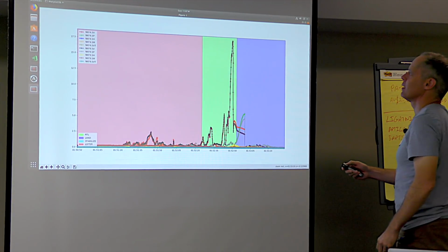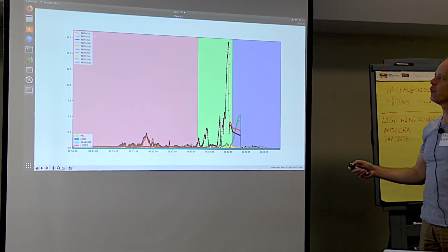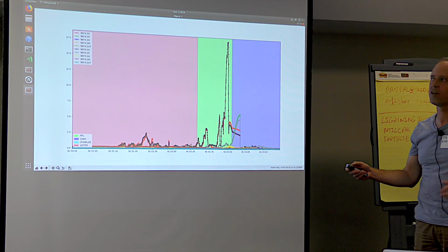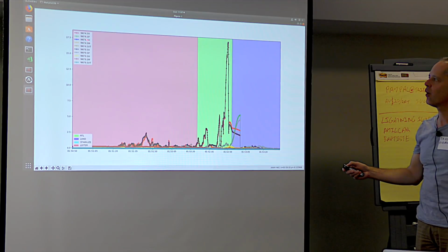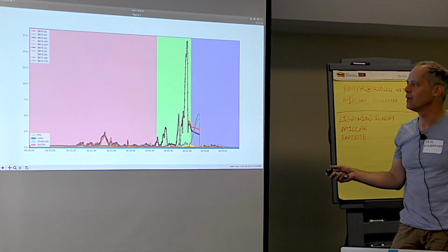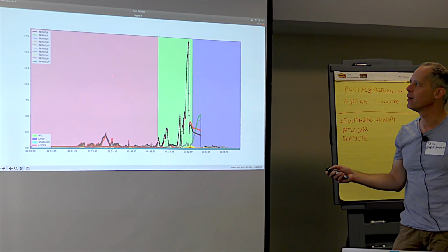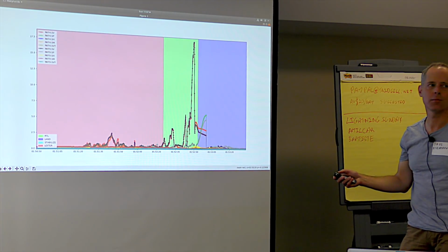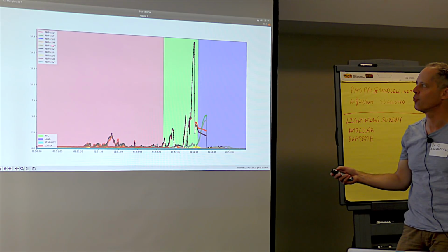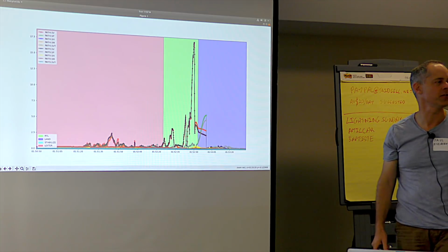What's to note there is that V stands for velocity, which is your GPS velocity. P is position, that's your GPS position. H is for height, that's whatever you've selected as your height. It could have been rangefinder, but in 99% of cases it's baro. And then M is essentially your magnetometer. Then we've got SVT, which is velocity T for true airspeed, which is only applicable for planes. And you'll notice that these are repeated again for the second EKF.